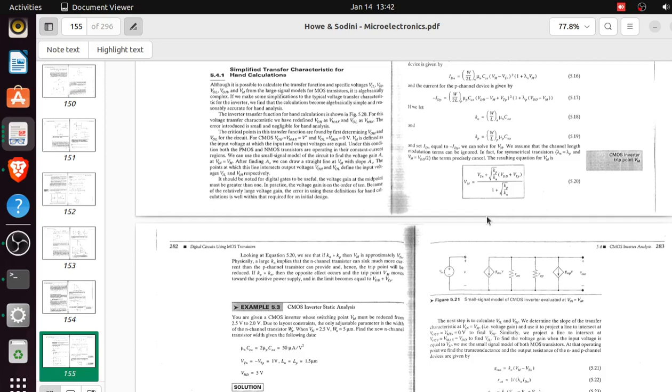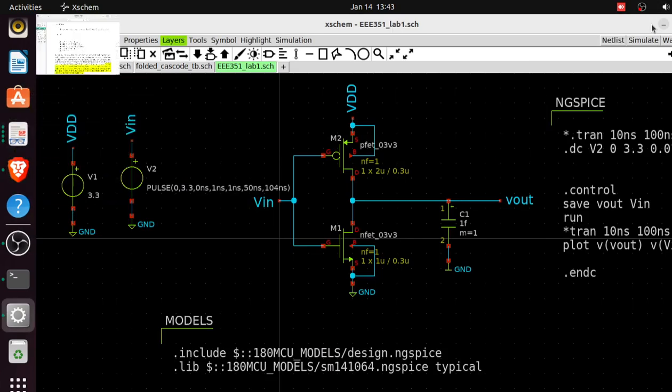We said for the best shape and performance, we let the transconductance parameters be equal, and the implication was that the sizing of the PMOS should be at least twice the sizing of the NMOS. So let's say now they are not equal, and let's make the sizing of PMOS lower than the sizing of NMOS. Let's see how it looks, and we'll do the other way around also.